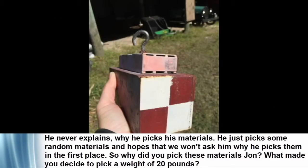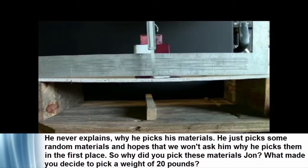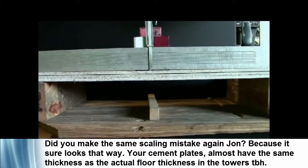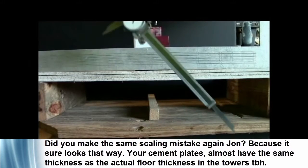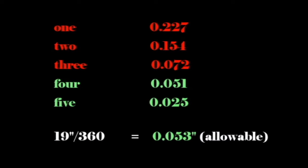But is that right? To test this, I used some cement-type planks and a solid block of steel that weighed about 20 pounds. Placing a steel block on the cement board, I measured the deflection for various numbers of planks. The plank span is 19 inches, and the maximum allowable deflection is therefore 19 divided by 360, or 0.053 inches. So the minimum number of planks needed to meet deflection criteria would be 4 planks for that particular design load.